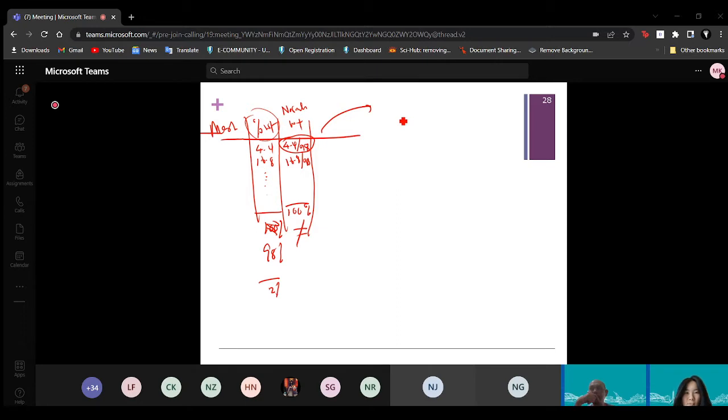With that 100%, this new normalized weight percent is the one you use when you calculate the n, right? For example, delta L over delta n, times the density times the weight percent. So use the new normalized weight percent. I think that is the only mistake that I haven't commented on. Most of you passed me your solution, but I just noticed that the weight percent is not 100%. So you need to normalize it, and then finally input that weight percent here to calculate your n, the number of crystals.